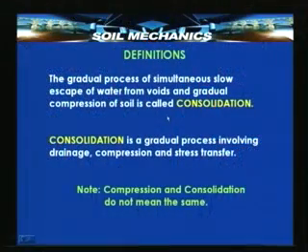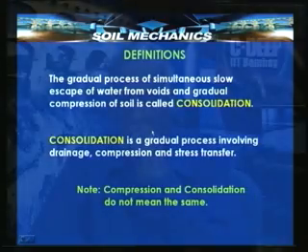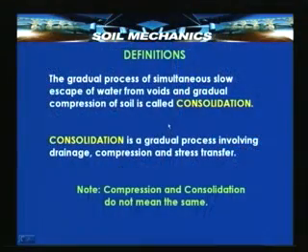Let us at this point of time make a formal definition, that is, the gradual process of simultaneous slow escape of water from voids and gradual compression of soil is what is called consolidation. So, there are two gradual, meaning time dependent processes in action, processes in play. One is the gradual process of slow escape of water, and simultaneously with this there is a gradual readjustment of particles and compression of soil, and this is what consolidation is all about.